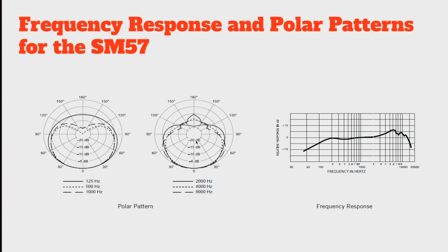And as we go over here into the higher frequencies, we can see that it stays somewhat cardioid-like, but we get some interesting effects that happen towards the rear null here, where it doesn't quite act as a null. Again, this is only to indicate that real-world microphones do not have a singular polar response. Their polar response will vary depending on the frequency of its input.